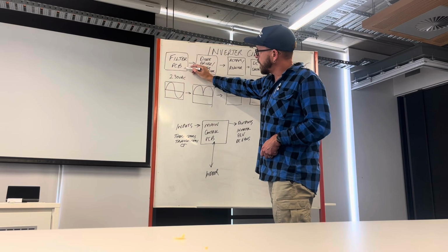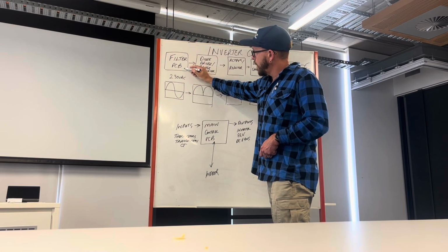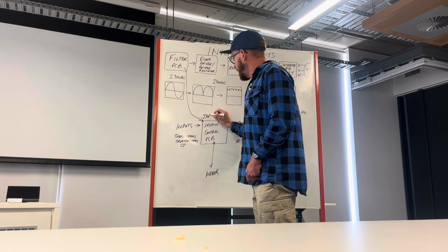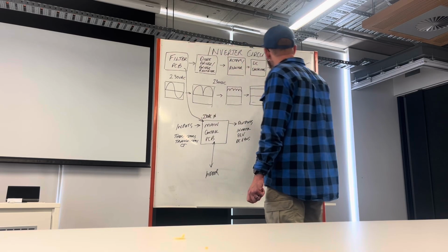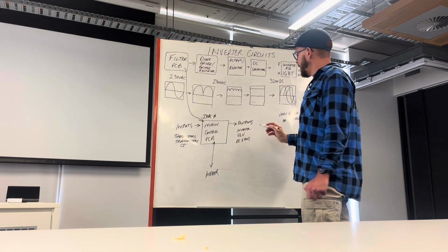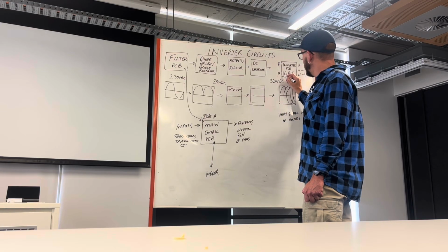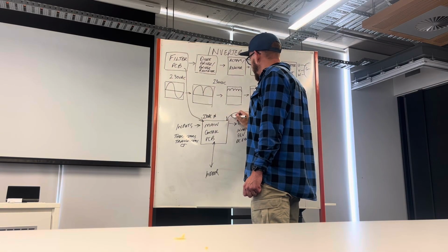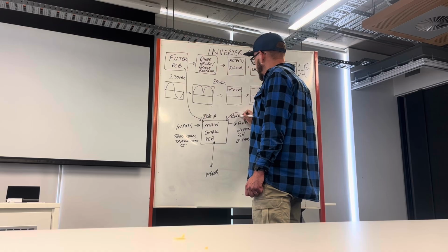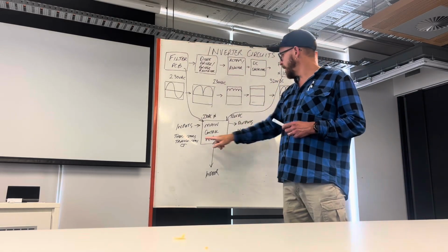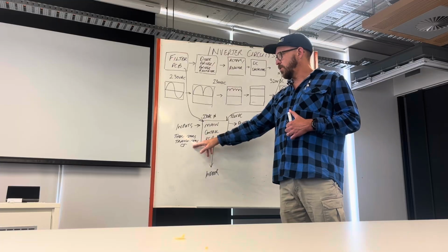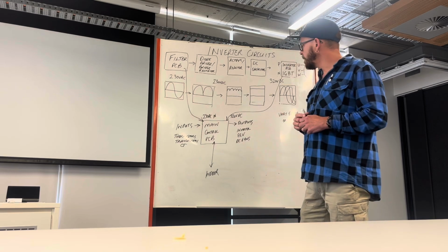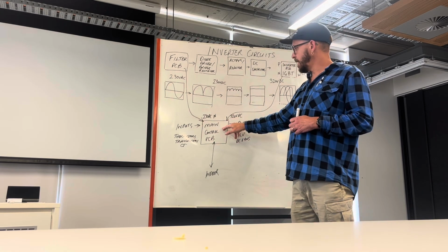So the AC voltage typically comes from the filter board, the incoming power, brings some 230 AC in, but it can't communicate unless it has DC voltage. So that comes from over here. It needs to also be getting that 320 volts DC in order to communicate. Some of these other communications are on different rails, so you might have 5 volt, 15 volt, but it needs to have the 320 volts DC here.